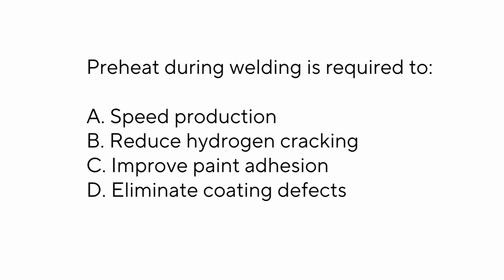Preheat during welding is required to: A. Speed production, B. Reduce hydrogen cracking, C. Improve paint adhesion, D. Eliminate coating defects. Answer: B. Reduce hydrogen cracking.